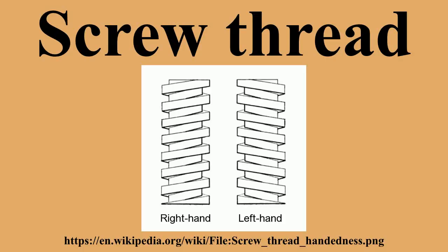If the pitch diameters of a screw and nut are exactly matched, there should be no play at all between the two as assembled, even in the presence of positive root-crest clearances. This is the case when the flanks of the threads come into intimate contact with one another, before the roots and crests do, if at all.